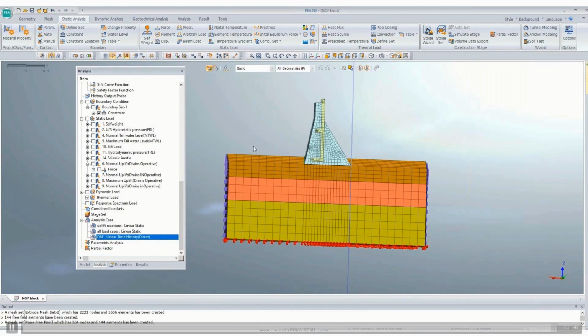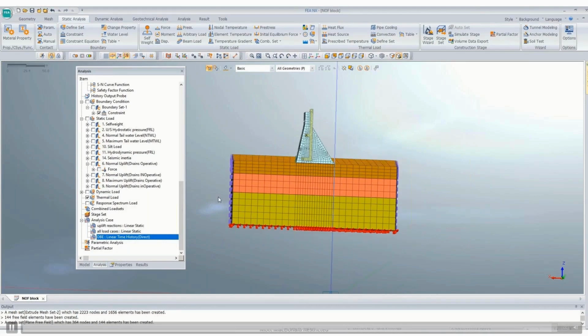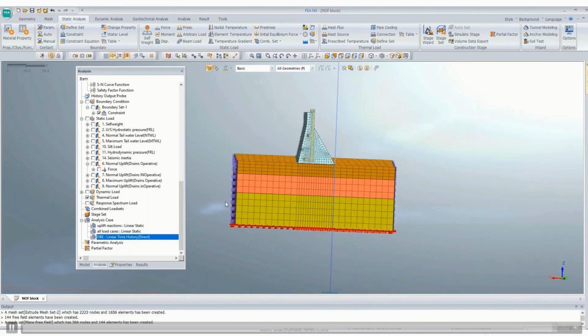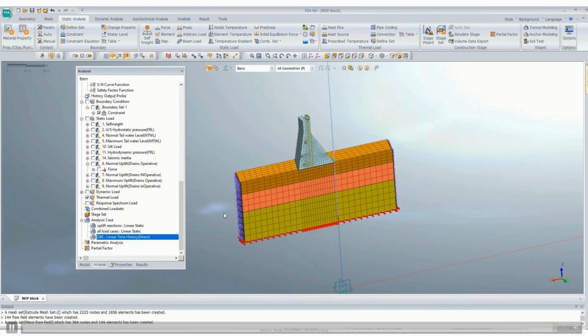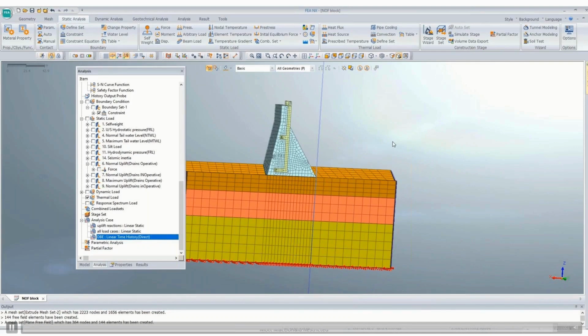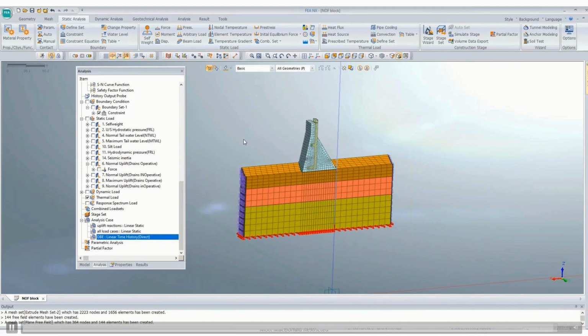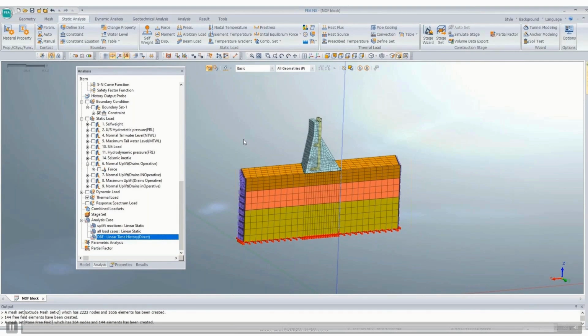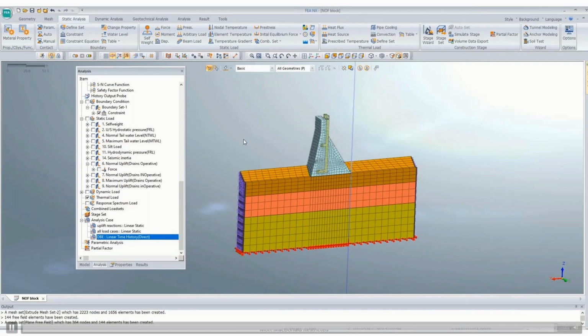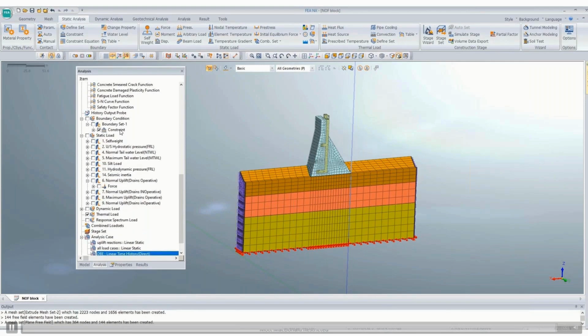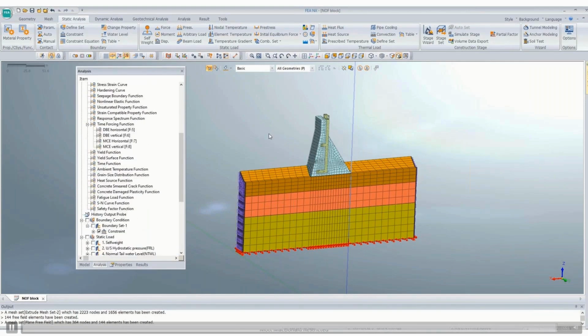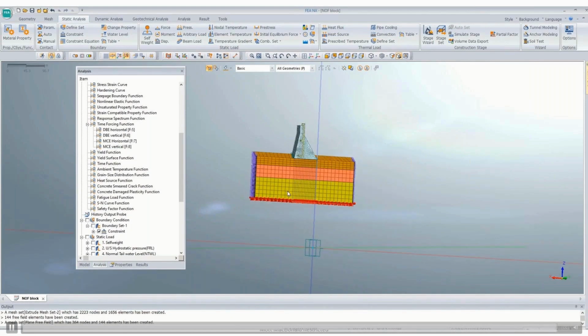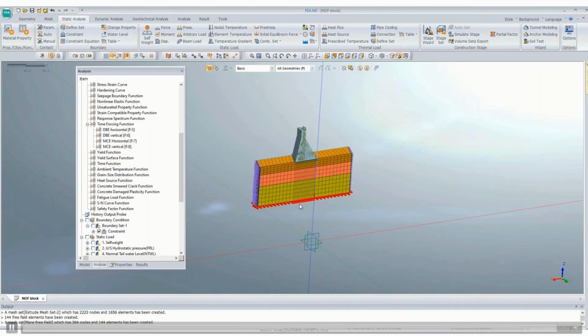So in the next session I'll analyze it, and then we'll check the stability against sliding for each cycle. Actually, it is not required for the dynamic analysis in frequency domain. It is mentioned in USACE Engineering Manual 6051. We'll go through that. But I'll perform this. Let's see whether the factors of safety are within the permissible limit for each cycle of this time history, even for the maximum ground acceleration, whether the sliding is okay or not. Okay, so this is it for this session. See you in the next session. Thank you very much.